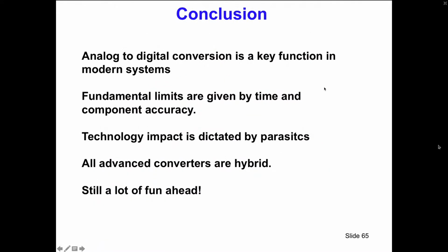Well, my dear friends, analog to digital conversion stays a key function in all modern systems. So designing A to D converters is still a very, very profitable business. Fundamental limits are given by time and component accuracy. We looked a little bit into that, saw jitter, saw metastability, saw mismatch, saw lithography. Technology impact is dictated by parasitics. That means that a good layout is still very, very valuable.